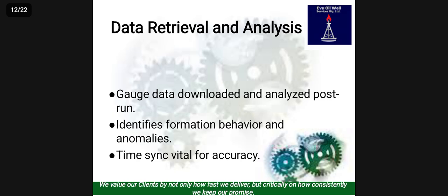Data retrieval and analysis. After the job, you download the data from the gauge and analyze it to see how the formation behaved: pressure buildup, leaks, or any abnormalities. Always make sure your time clock matches surface records for correct analysis. If time doesn't match, your data curve will lie to you.